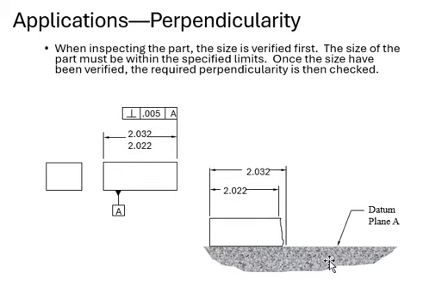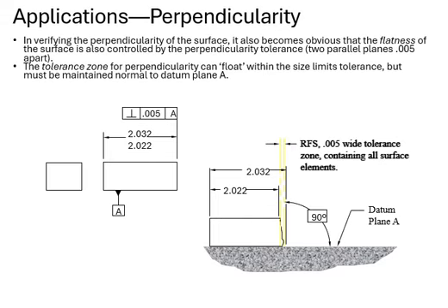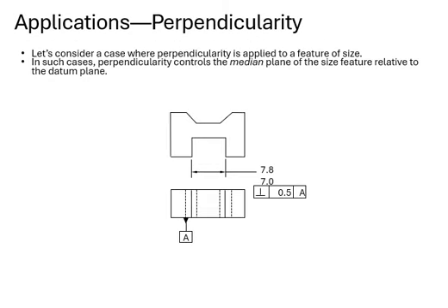We're going to bring our surface gauge, then identify this plane, datum plane, from which we're going to measure this perpendicularity. Perpendiculars usually make a 90-degree angle. We do the same thing here. We're going to draw our zone. You have a size, and you also have the perpendicularity tolerance zone, which is like 0.005 away. And of course, here's the 90-degree angle I mentioned previously, which this surface and that surface are going to make, okay?